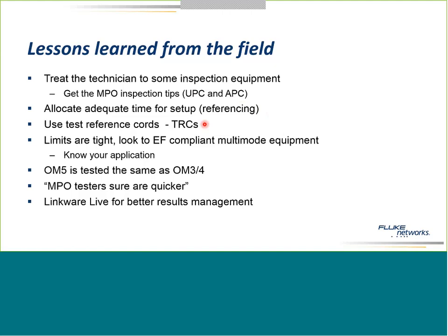Make sure your test reference cords are in good condition. Make sure they've got reference grade connectors on them. Make sure they are encircled flux compliant. That's going to help with those tight limits.